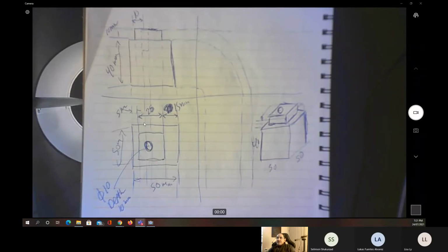Now, let's check out how we can do the code for this part. As you can see, we have just a small square shifted aside on the top of the larger cube. The process is going to be very simple. We're only going to do the offset of the square by the radius of the cutting tool. Definitely, we are going to have one square, then one line. So the cutting is going to be very easy. It's one square and one line to remove the rest of the top.